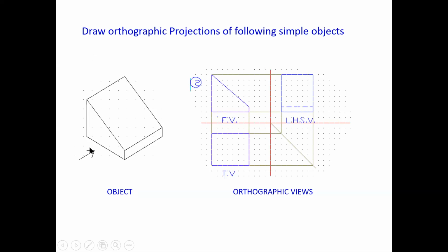So this front view should be on this side. Looking from this side, drawing at this side. Here is a y-axis and x-axis. Getting? So if you look from the left, you have to draw it on the right, and if you look from the right, you have to draw it at the left of this y-axis.